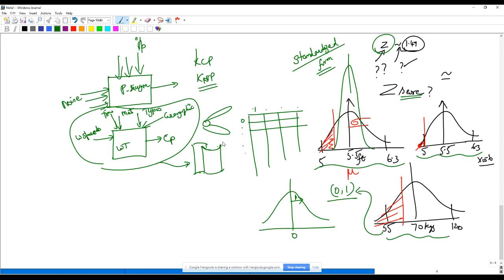The third one is tolerance design. Obviously, the tolerance design comes from a manufacturing perspective. That's exactly the whole point, right? What you see on the computer is not what you get on the field. I might give you some dimensions, but the manufacturer's limitation might not allow them to produce. That's why they ask for tolerances. So you'll have to account for those tolerances to begin with. You cannot have your design that says that it will only accept 5 mm. It has to accept both 4.8 and 5.2 mm. That's the whole point. Okay?